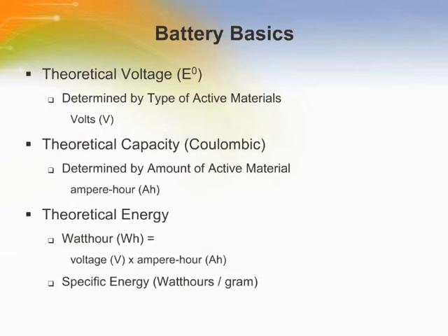The ampere-hour capacity of a battery is directly associated with the quantity of electricity obtained from the active materials. The capacity of a battery can also be considered on an energy watt-hour basis by taking both the voltage and the quantity of electricity into consideration. This theoretical energy value is the maximum value that can be delivered by a specific electrochemical system.